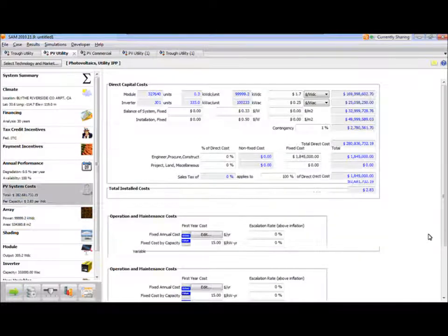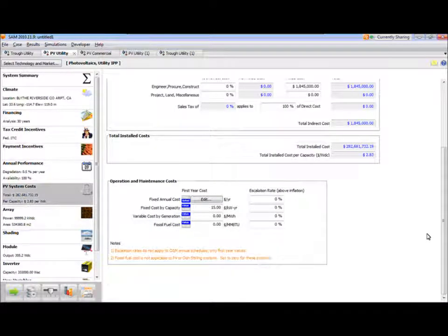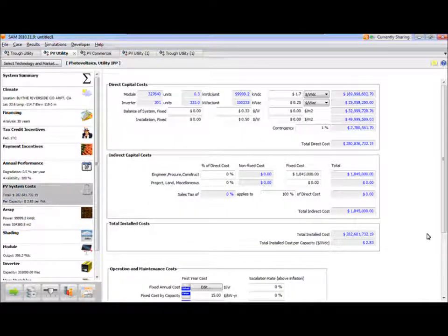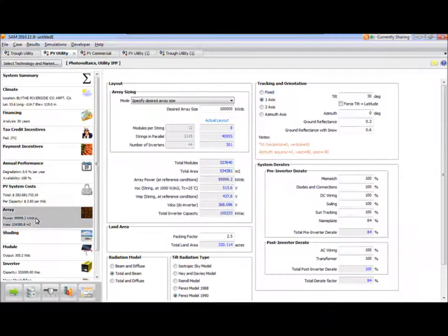And will it pick up the axis by itself, or do I have to specify anything? Because the dual axis means it is going to track the movement of the sun in either direction. Right. So if you change the option here to dual axis tracking, this takes care of the performance part of the model. So the model will make sure that it's pointing the array at the sun.